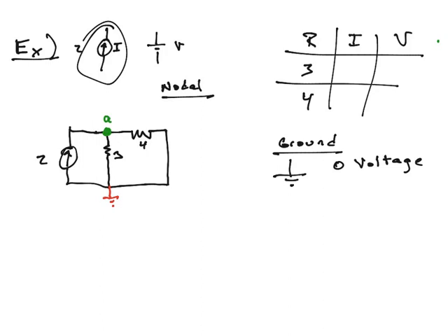Okay, where else can there be a node? This can be a node here. But notice, again, all of this is just wire. So really, all of that is the same big node. But this is the thing. Because I chose a ground already, the ground acts as a node. So all of this stuff is all the ground. That's all the node called the ground.